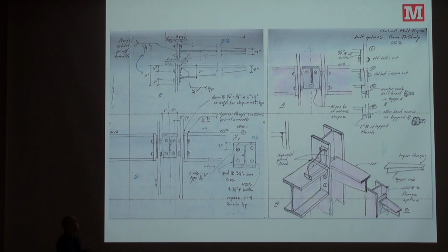So we need to introduce a little shim space here so we can plumb and align this building, because we can't go hack at it and we can't hide it with finishes, because we need a certain level of precision to fit within the window. We even need to figure out a way to waterproof it, so we made this gap, this shim space, smaller so you could go in and caulk around it.